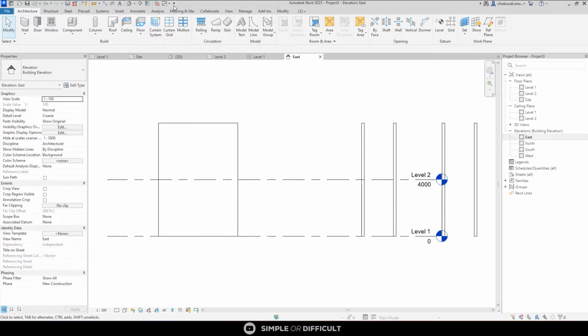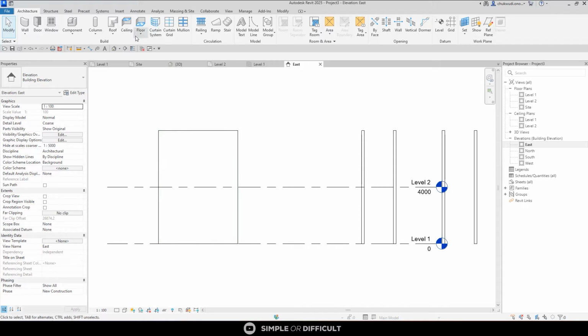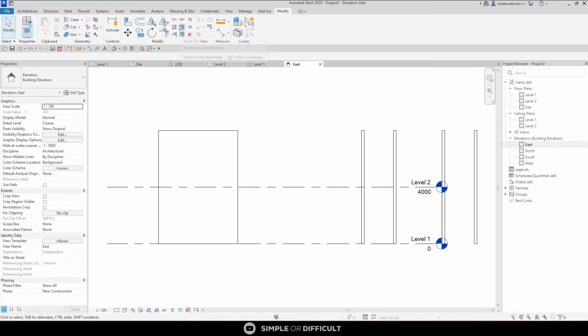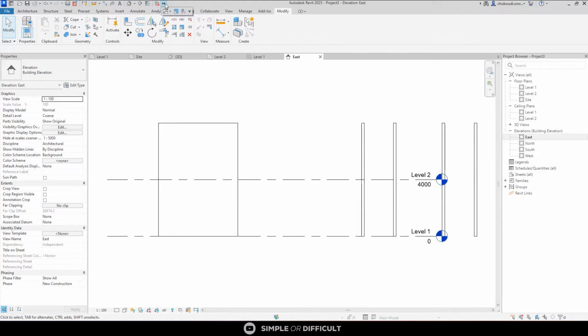All right, remember I told you that you can add new tools here. To do that, just come over here, get to any tool you want, right click, you see add to quick access toolbar, and when I add it, you can see it has entered here. You can add the align tool too. But it is only showing because it's here. If I take it back up there, you see it doesn't show. So if you want it to show, you just click here and then select all those ones that you want. All right, so that is enough for user interface. Let's get on with the tutorial.